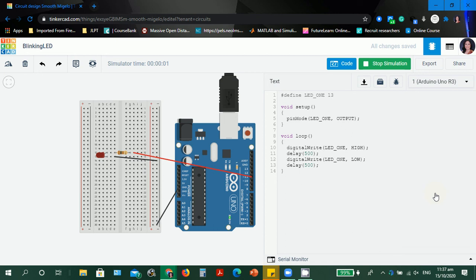Actually, this is a problem. It's not really a runtime error, or somewhat a runtime error, because the error is not found in the Arduino sketch but in your setup. So you've declared it as 13, then you're going to ask why it's not working. So you have to check. Since it is pin 11, it should be reflected in the sketch as pin 11 also.